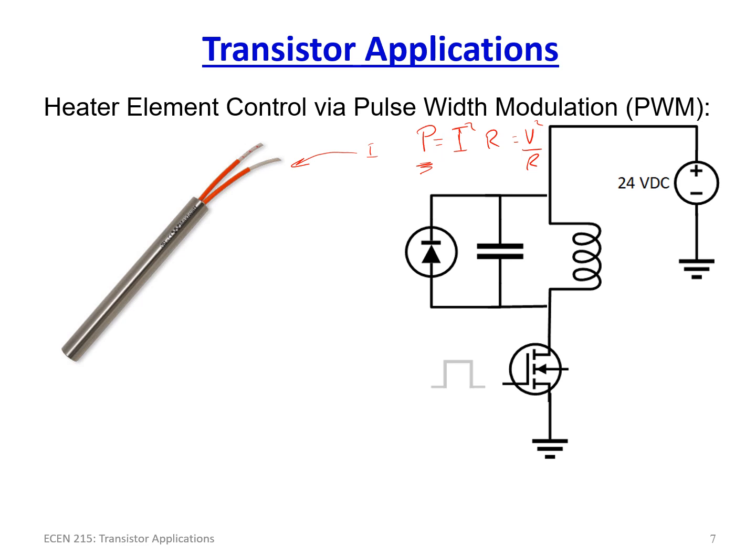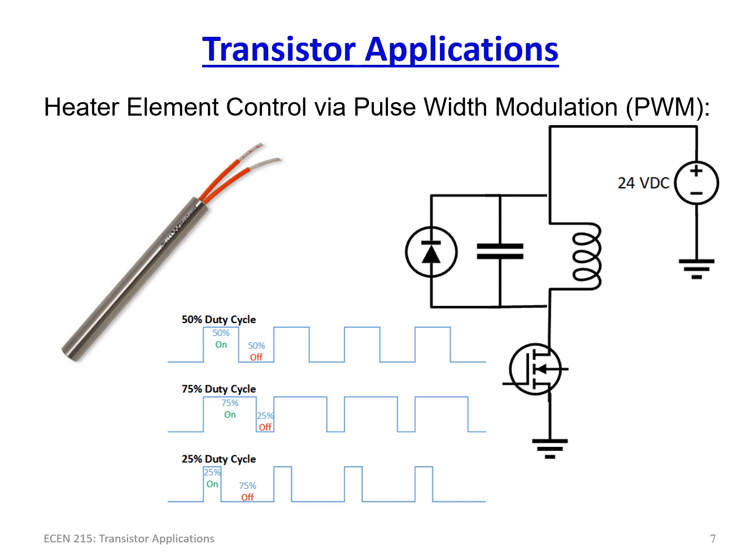I can make an op-amp circuit, for instance, to control it. The problem with an op-amp circuit is that I'm either going to use that energy in the heater rod or in the control for the heater rod. So either way, I'm dissipating the full load. Or I do something called pulse width modulation. What that refers to is the amount of on time that is provided.